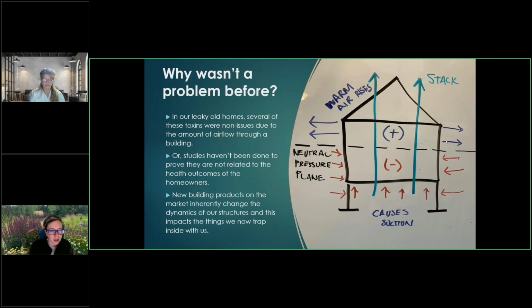And I'm using radon because that's big for me, but also we're going to talk about carbon monoxide and other things. I like this diagram too because it feels really obvious that it's going to draw it in from the bottom and blow it out through the top. This is fairly common. So this is why I often say boots and hats, right? That's what you wear in the wintertime. Really addressing the top and bottom of your structure is going to make a big difference, bigger than replacing your windows.